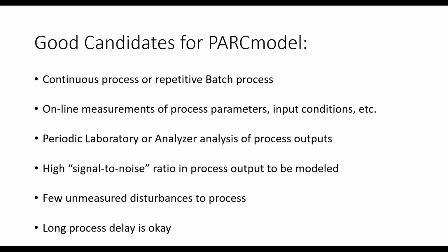And the last thing to know, and this is important, is that long process delays are actually okay in Park Model. Park Model has the ability to handle long process delays within the calculations and account for those. So it's not a problem if you have a long input to output delay time in your process.